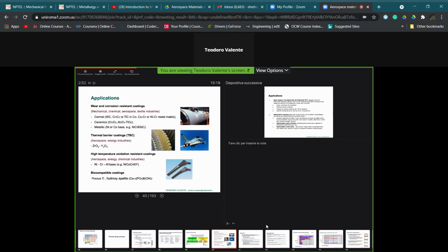When we do have non-oxide based ceramics, one of the issues is that usually non-oxide based ceramics, if they see oxygen during the fabrication process, undergo a deterioration phenomenon. Just an example, if you have carbon inside the non-oxide ceramics and carbon sees oxygen, it can form, for example, carbon monoxide, carbon dioxide.